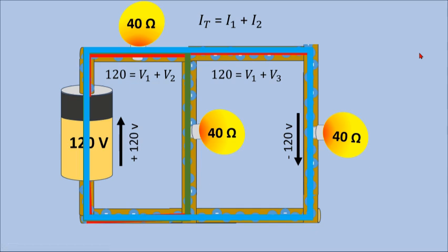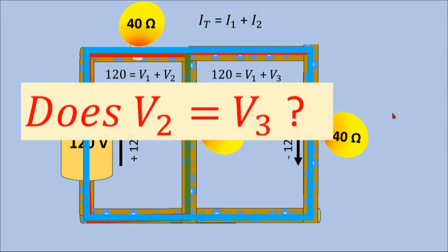All right, so now we're kind of stuck because we don't know how much current goes down here through the second light bulb, and we don't know how much goes to the third light bulb. We don't even know how much goes to the first light bulb. So we don't know the current anywhere. If this was a series circuit, we could just add the light bulbs in series. If it was parallel, we'd add them in parallel. But it has aspects of both, so we can't do it that simply. But what we can do is combine resistors.